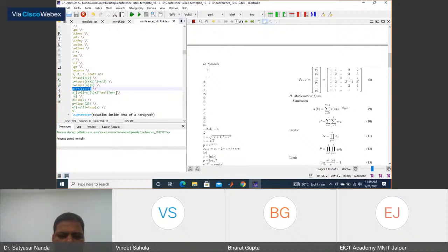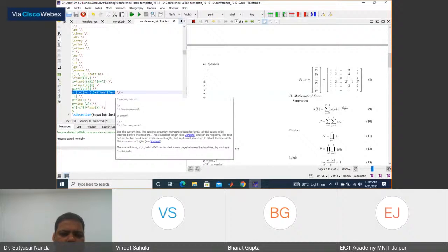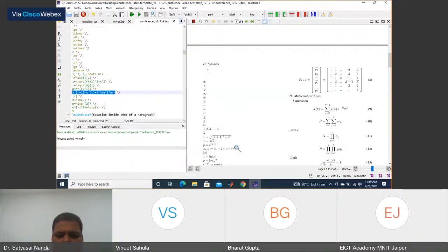Then the famous LMS algorithm in adaptive signal processing or any machine learning equation, that is x_{t+1} is equal to x_t plus 2 mu times input times error. That is the update equation. This is how we write x underscore t plus 1: the time instant t plus 1 is dependent upon x_t plus 2 mu times input times error signal. So any update is dependent upon the error.